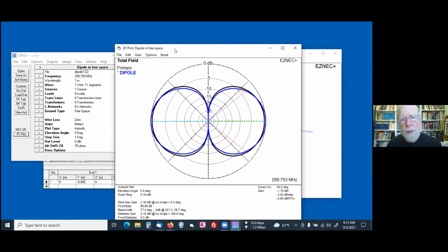So why don't short antennas do as well as long antennas? Well, the reason is they're not as efficient. And the reason they're not as efficient isn't anything to do with the radiation characteristics. It's just the fact that in order to get that kind of field radiating from such a short antenna, you've got to have humongous currents flowing in it. I don't have the graphics right here, but it takes something like 600 amps to radiate 100 watts. And so your I squared R losses eat you alive.